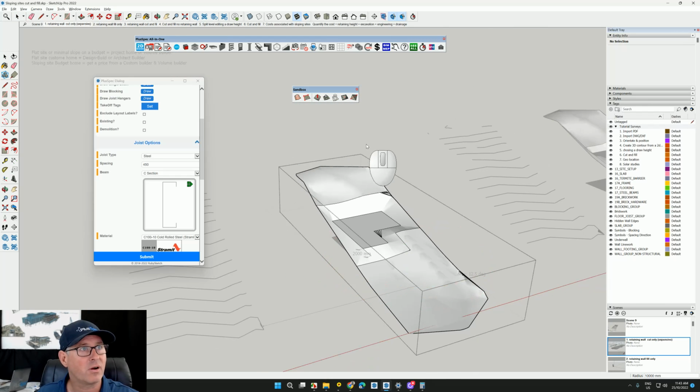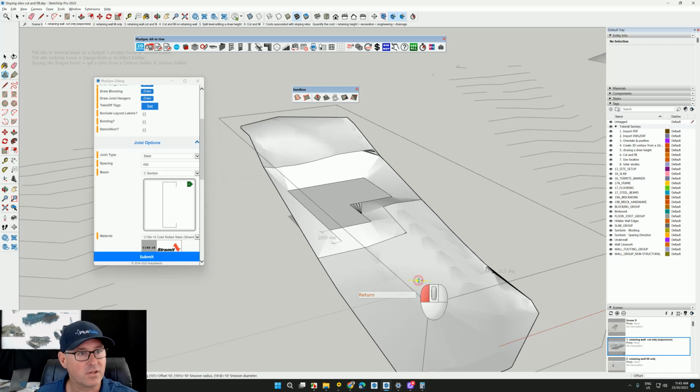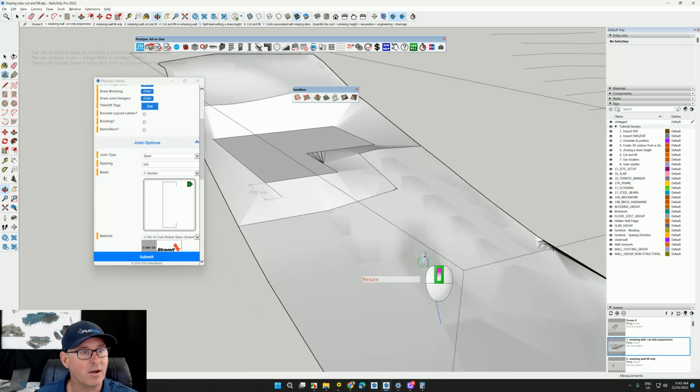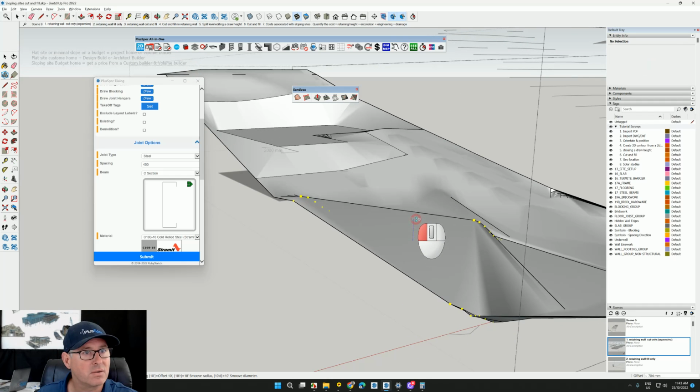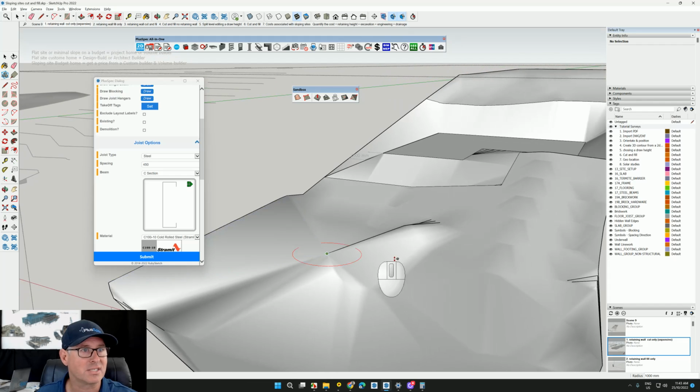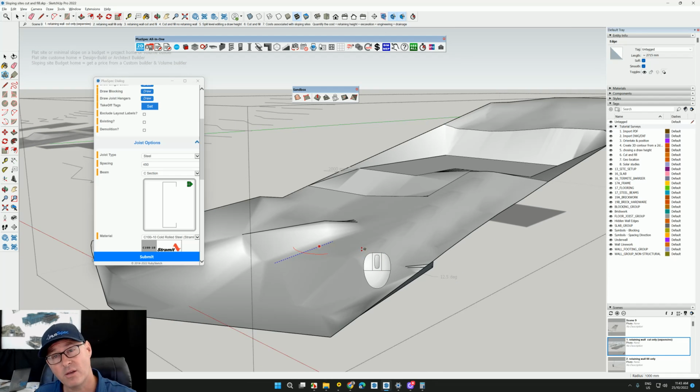This one here, I'm going to change particular areas, and you'll notice the radius at the moment is 10 meters. I just want to make it 1 meter. Enter. And now you notice that the radius is 1 meter, and I can change that terrain according to the radius that I select. Guys, I hope it helps you get ready to start designing homes that are specific to the block.